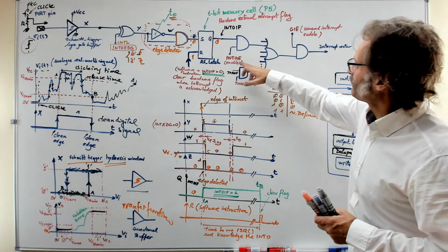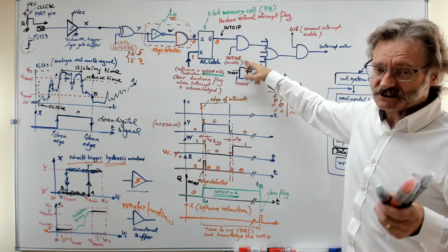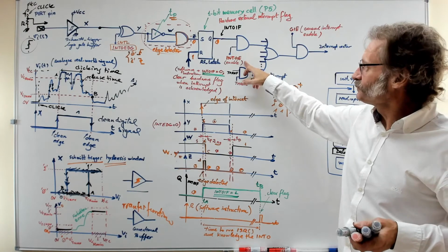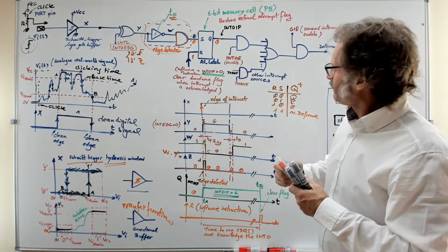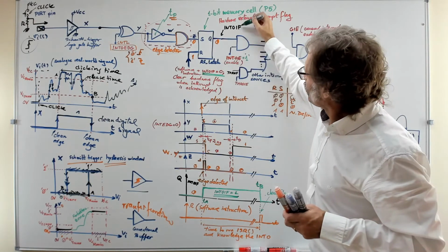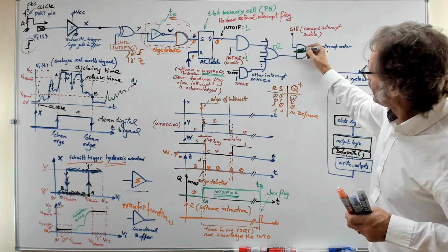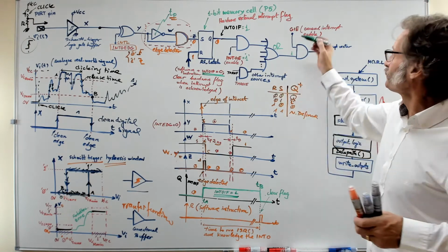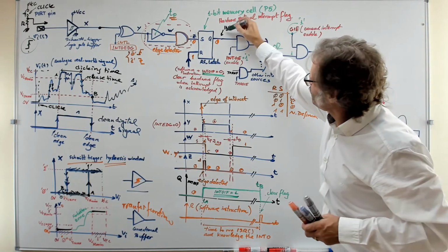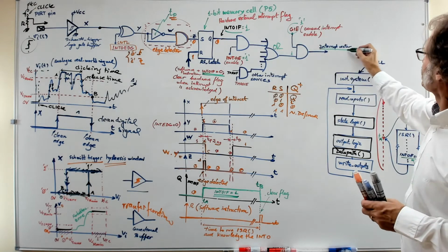And you can do that with the external interrupt 0 interrupt enable bit, just another bit in another interrupt configuration register. If this is 1, for example, if this is what you do in the software in the init system, the edge you've got here is able to go through this OR and generate, if you have the general interrupt enable also enabled, you see, an interrupt vector through the logic of the interrupt system.